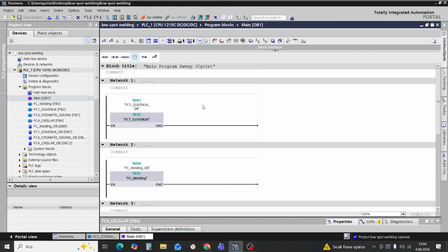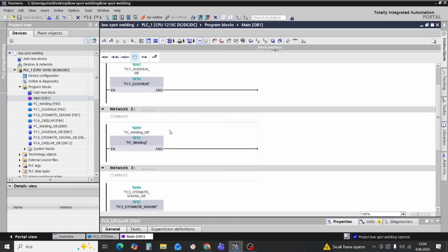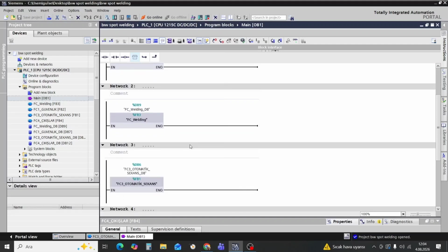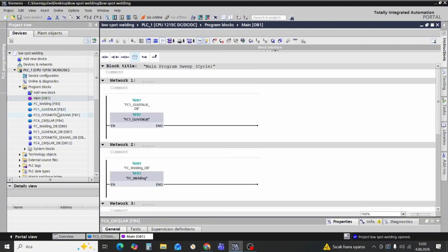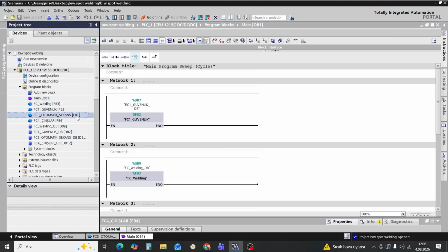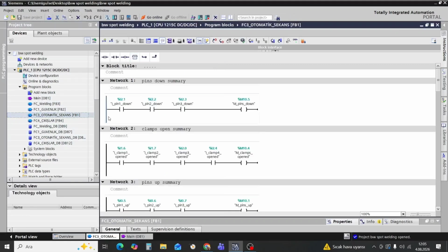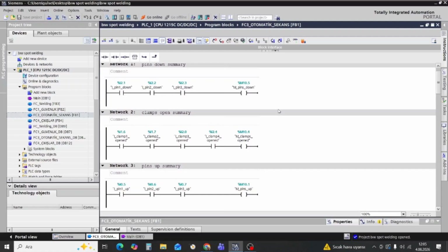Now we can go through the program in TIA Portal. Starting with the main operation block, here I call the function data blocks. Each checks a specific operation, so this is actually where you build the most. I've divided this operation into 4 sections, and we're going to take a closer look at each of them, but right now I'm going to start with the automated sequence. Also, an important note is that you should always start with that because this is like the skeleton of the project.